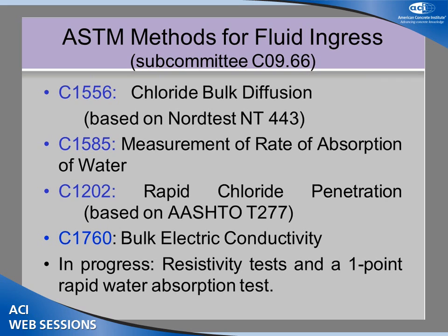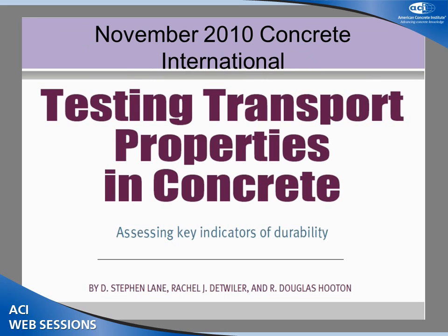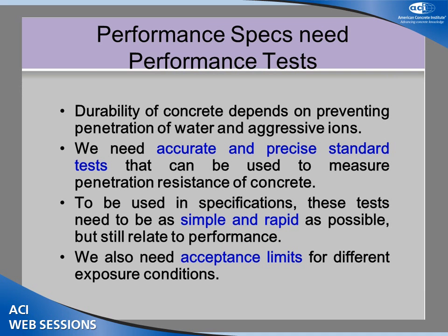And we're also looking at several resistivity methods, and we're looking at a rapid absorption method. We summarized some of this about 2 years ago in Concrete International. I worked with Steve Lane and Rachel Detwiler. We wrote a paper discussing some of the various transport mechanisms and how they're measured, and talking about ASTM methods and other methods as well.